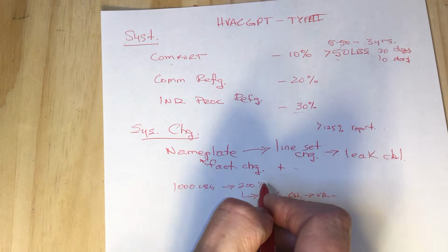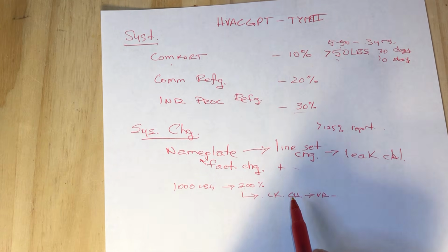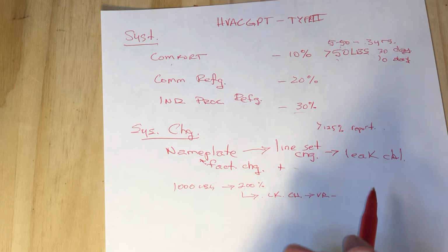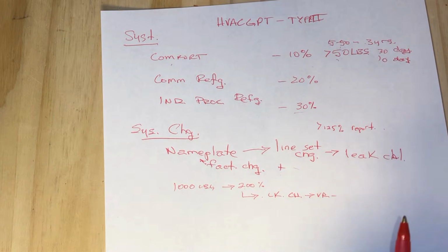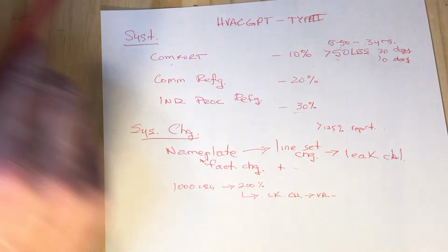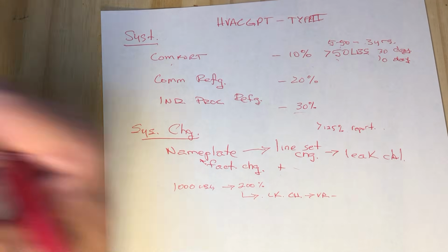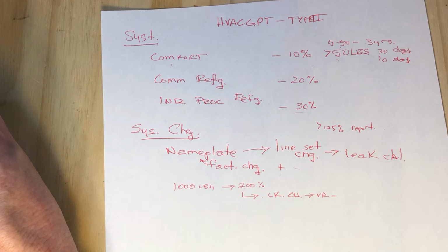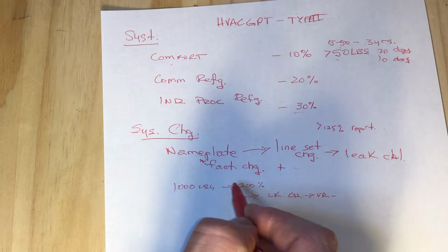But let's say that you put in less than 200 pounds of refrigerant within a calendar year, then there's no requirement by the EPA, if it's a commercial refrigeration unit, to fix the leak at this time. And the same for the 5 to 50 pounds, but you probably should do so for environmentally good reasons.